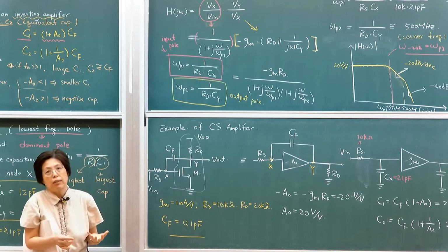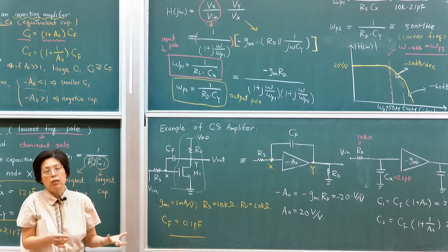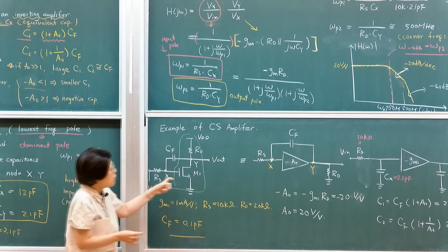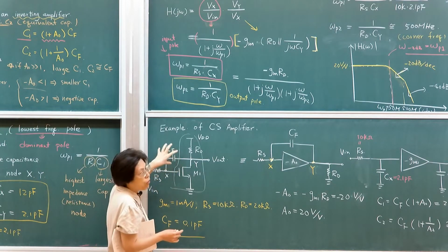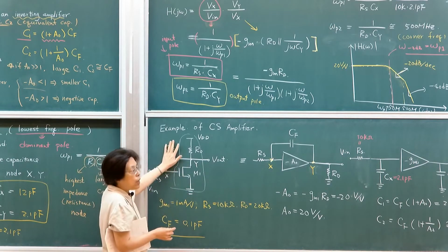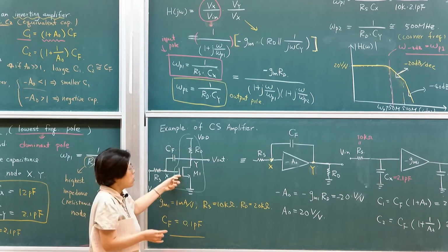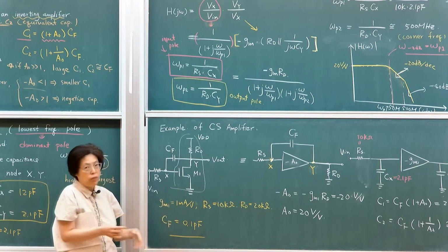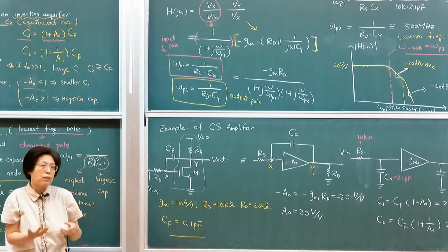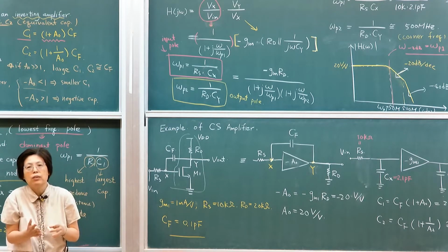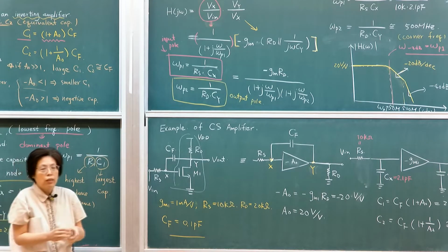But in other cases, we're not deliberately adding capacitance. If you're having transistors, they already come with capacitance. These are called parasitic capacitances. So we need to go back and revisit. These are externally added capacitances. But what if, without this CF, the transistor actually comes with capacitance, especially for MOSFET? If you think about it, it's a parallel plate capacitance built into the transistor.